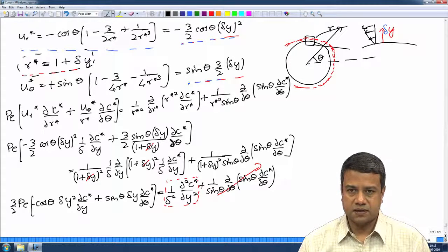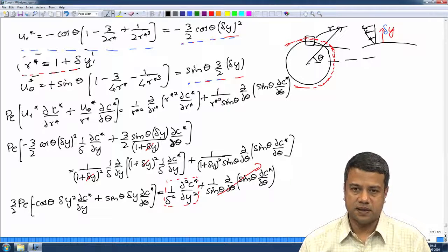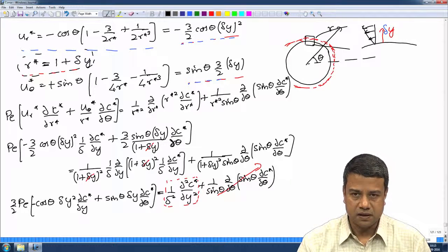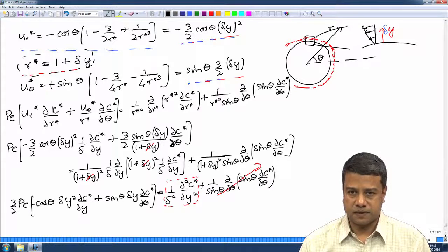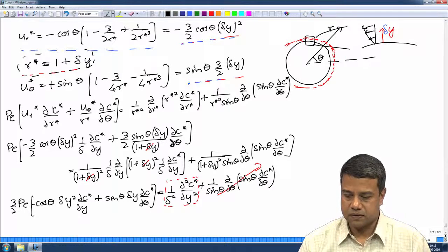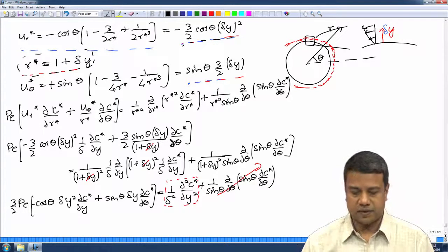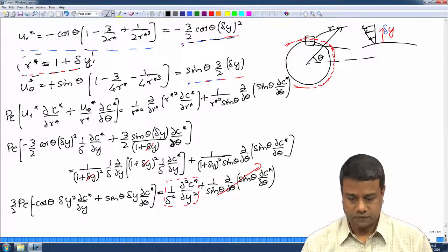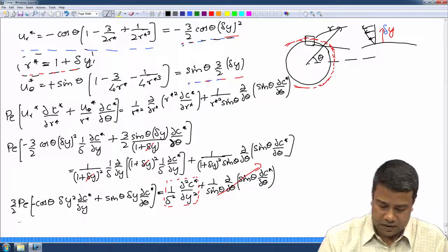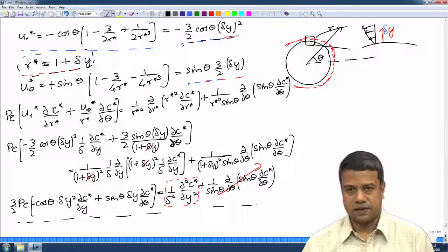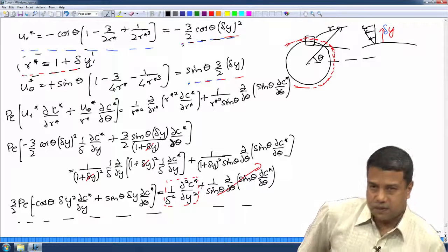So this is not surprising. The no slip condition implies that the tangential velocity is linearly increasing from the surface, and as I will show a little later, it also implies that the normal velocity goes as the square of the distance from the surface. We had inserted this into the conservation equation in order to get a balance equation.